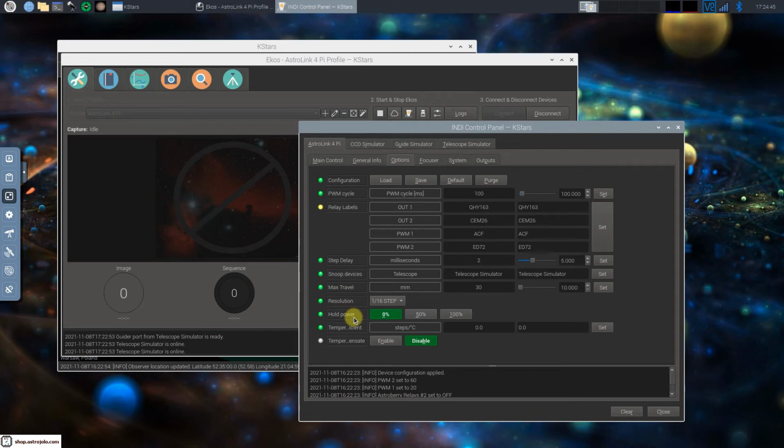Well, next thing is hold power. So when the stepper focusing motor is not rotating, it can be held in the position with some predefined power. It can be set. The values that are presented here depend on the device revision. If you're using unipolar motor with gearbox, the recommended hold power is 0.